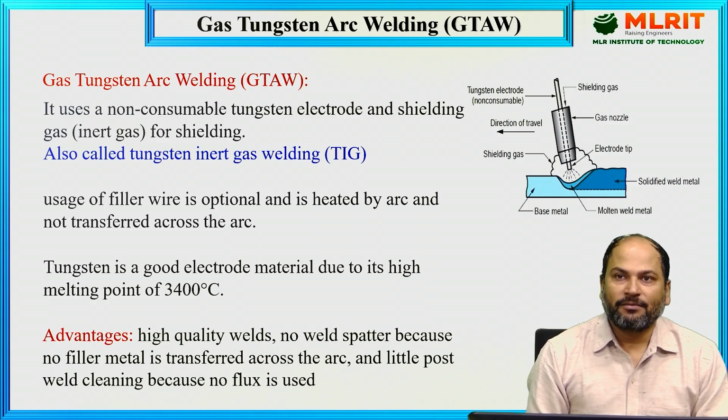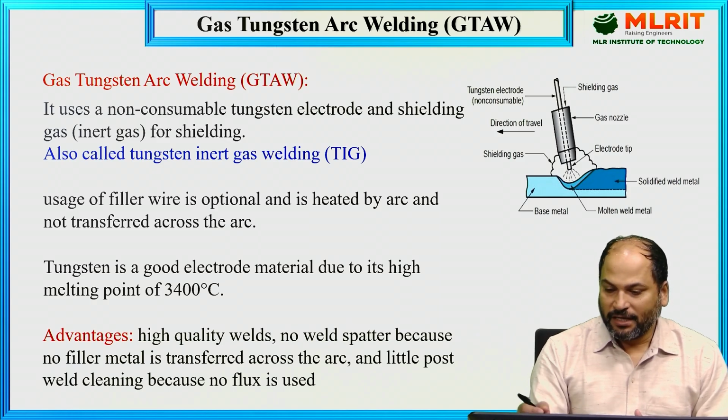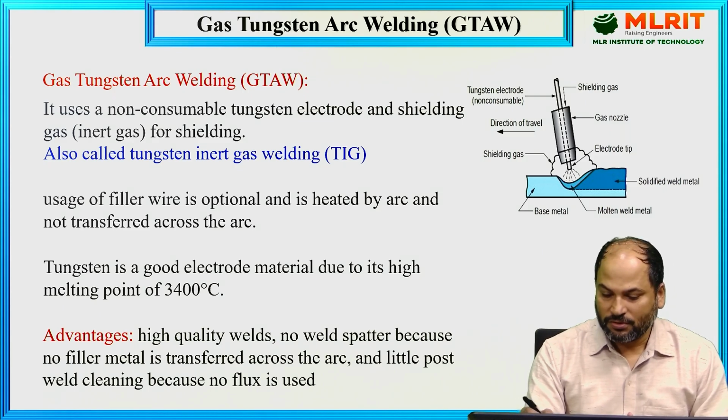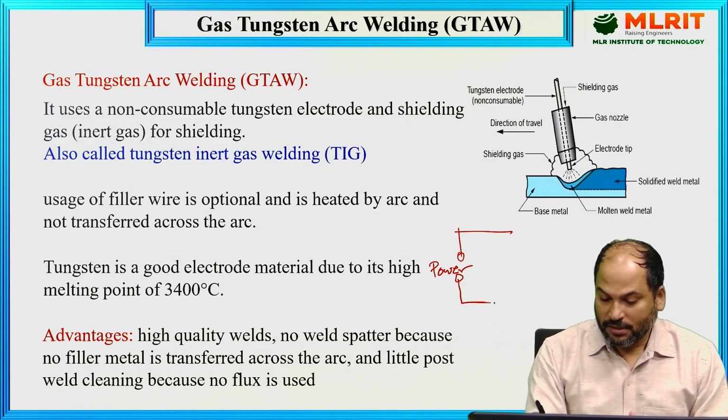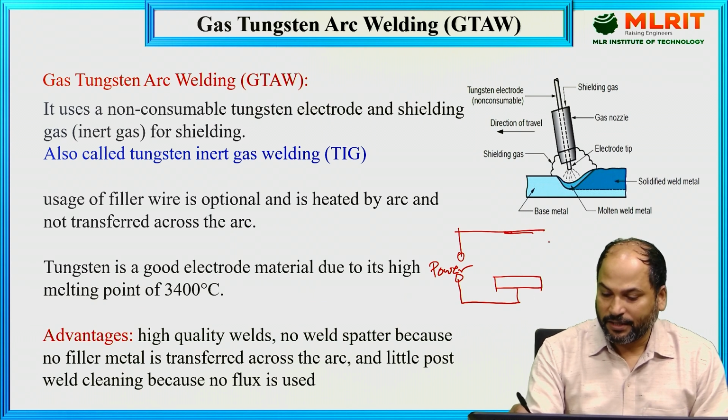This is arc welding. We have already discussed it through a diagram. It's a simple diagram I'm going to draw, so things will be more clear. This is the power source. The positive terminal will be connected to the workpiece which we are going to weld, and the other part of the source will be connected to the electrode holder, simply a device used to hold the electrode.